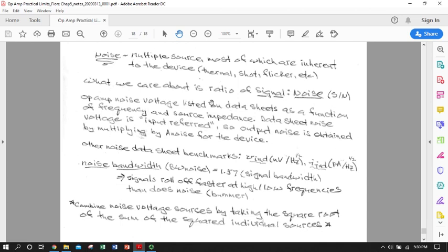There's a quantity that we can define as signal to noise, and it's the relative magnitudes of whatever signal you care about to all the sum total of the signals you don't. And you will see this frequently in all branches of science, but definitely in electronics. Signal to noise is the quantity you're trying to optimize. Since noise signals are signals, they have the same kind of considerations in terms of bandwidth, gain, everything else, because they are voltage signals. And there are branches of science that use them as data sources, in which case you could argue that they're not noise.